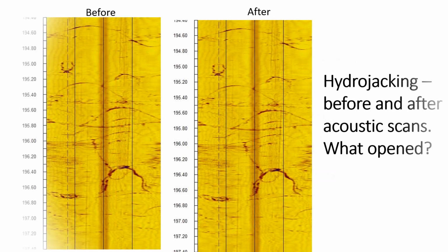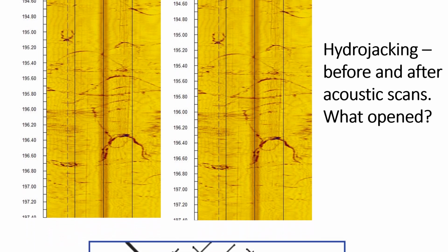If several fractures of different orientation can be tested, it is possible to build up information on the stresses in different orientations and to obtain some bounds on the possible stress tensor. More usually, there are multiple fractures within the straddled zone or intersecting fractures, so that multiple closure pressures are detected in the pressure decline, and there is always uncertainty about which fracture set is closing.